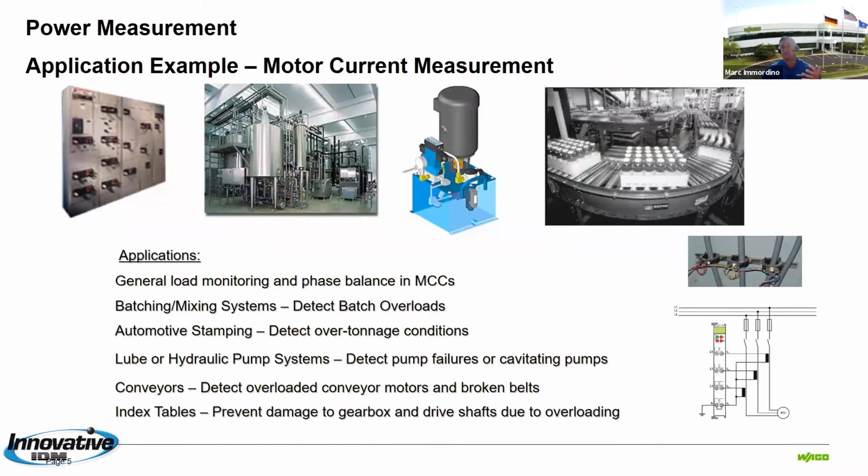Another is the motor current measurement data, which can be used to detect instant or cumulative loading to protect an installation from potential failure. So you're constantly monitoring, looking at these systems, overload conditions that can be easily detected, initiating a system shutdown to prevent costly damage to the equipment. So, if you see binding or anything like that on the load side, of course, you're going to see an increase on your energy usage on your motor control circuits.